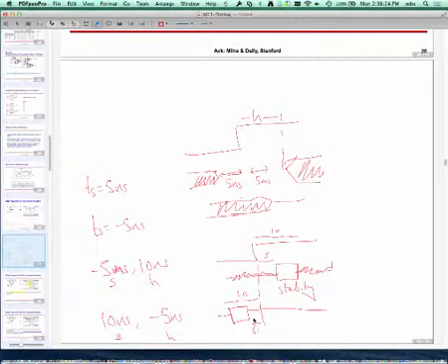Then it's fine, right? The whole data line would be shifted by that amount. So these negative values, it appears that magic is happening. That is, somehow the data is getting sampled even though the clock doesn't come into the future. What's really happening is inside the circuit, the data has been delayed before the clock gets to take a look at it.